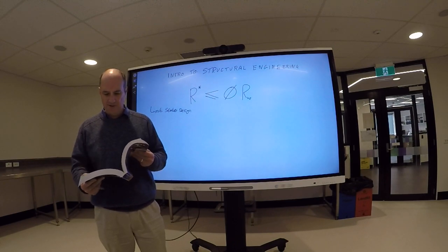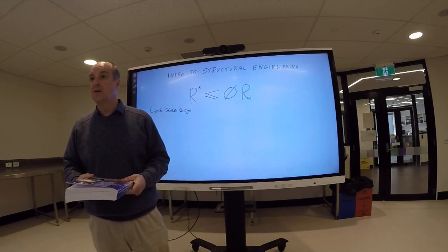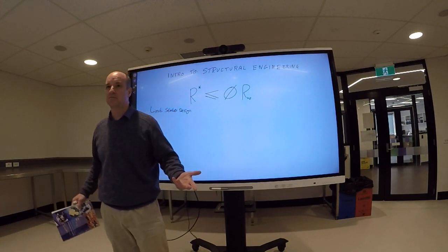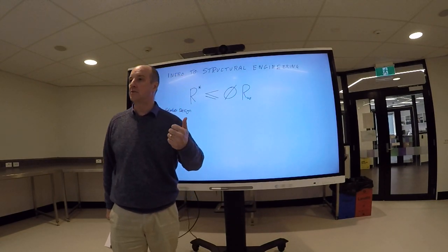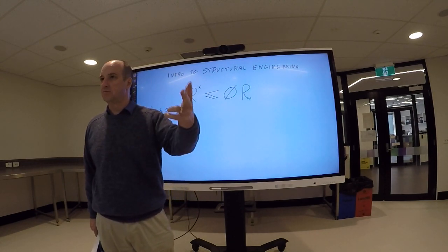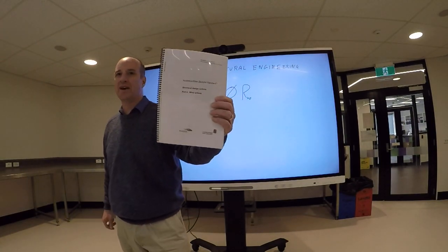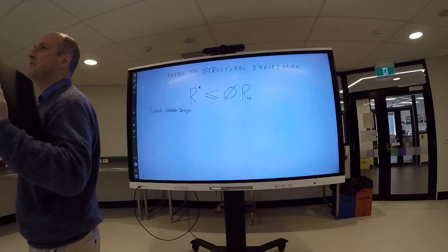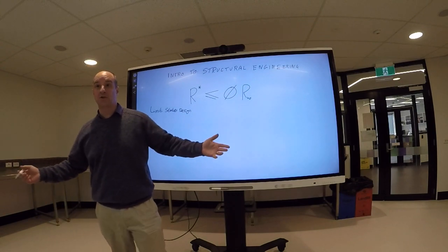Okay? So 1170 is a set of loads called the loading code. There's 1170.0, which is all about structures and loads and how you design. 1170.1 is all about your dead loads, your live loads, and the kind of actions that happen. 1170.2 is this one. It's called wind actions. 1170.3 is earthquake, 1170.4 is snow loads, 1170.5 is, I've forgotten what it is. Okay? So 1170 covers basically all the loads on structures. That's what it's all about.